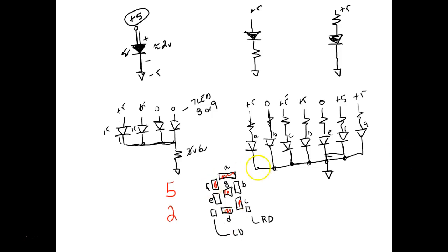But what I'd have to do if I changed over to a 3, then I would have to come over and do this. Now, what we're using, so we have decoders that will take a binary input and automatically turn on the segments to display the numbers, the binary number that we put on the input. Now we have a 7448. This is a common cathode driver, decoder driver.